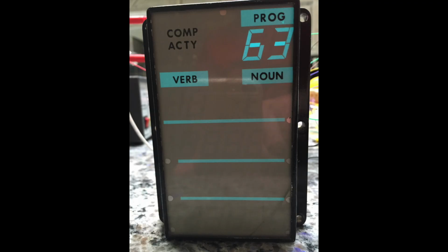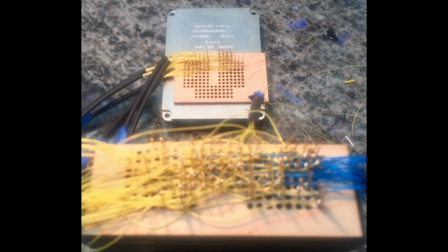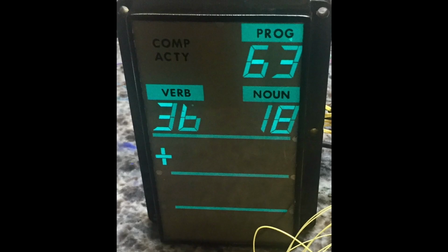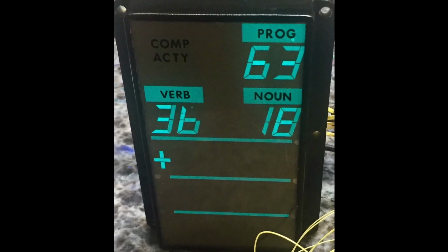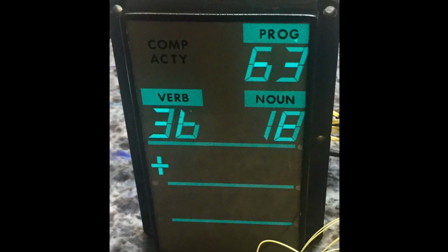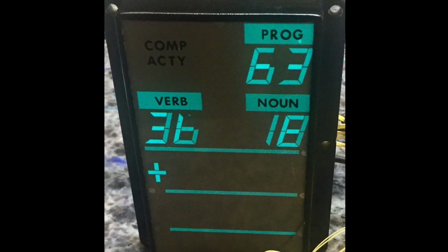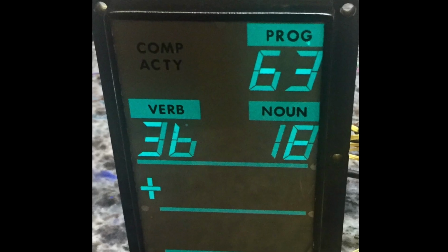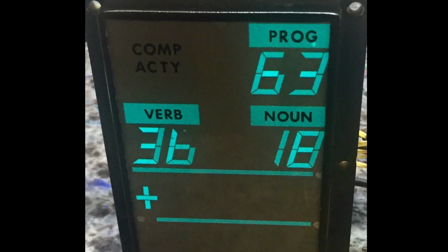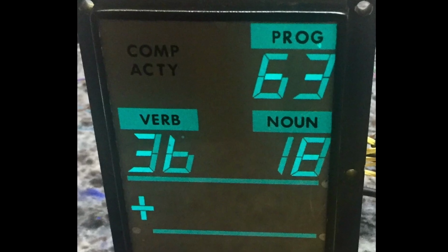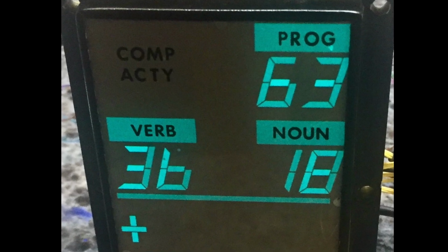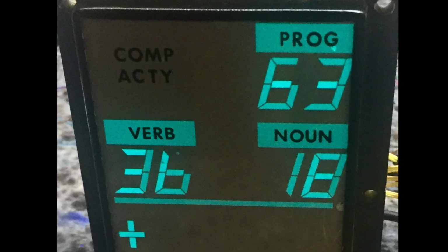We started to see pictures with actual numbers, program 63, then Carl wire wrapped some more, and we got this gorgeous display. You can still see the limitation of the prototype though, with some non-uniformity. The top of the 6 is not lighting up, and the color appears bluer than the period pictures. We confirmed that this was indeed a property of the early displays that were spec'd for a wavelength of 510 nanometers, which is quite blue, while the flight ones were spec'd for a greener 530 nanometers. At this point, it was time to plug in the precious flight qualified display, and we got this picture.